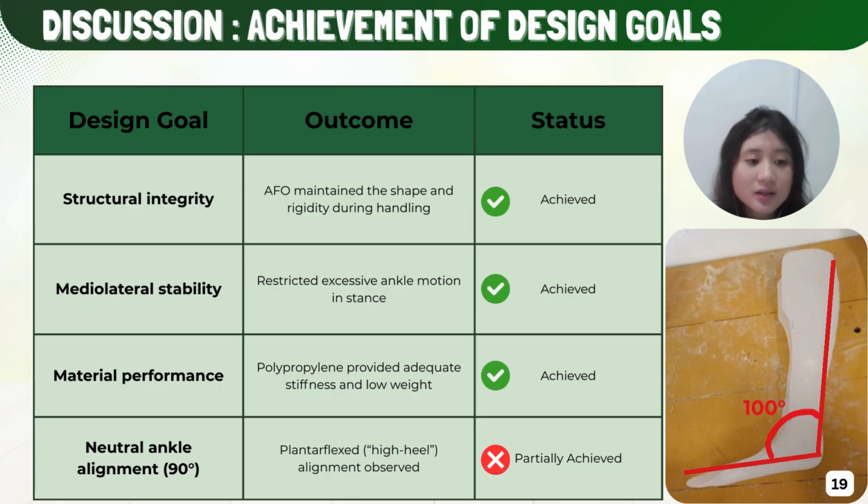The rigid solid design effectively resists excessive ankle motion during stance phase, which is consistent with the primary function of an AFO in drop foot management. Third, material performance met expectations. Polypropylene offers a good balance between stiffness and low weight, supporting ankle stability while minimizing added limb mass.